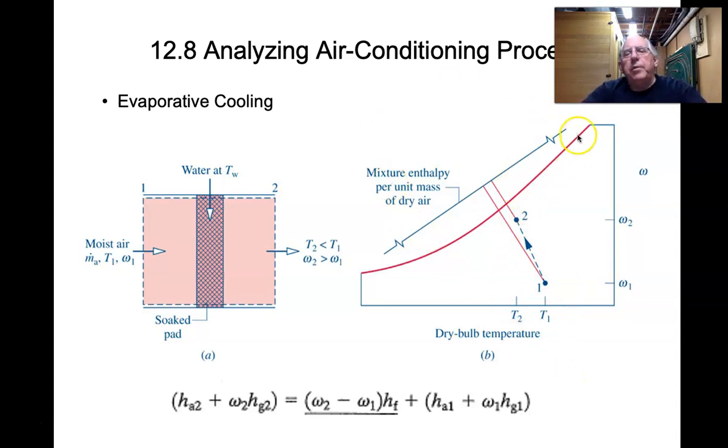And in this particular problem, as they show the mixture enthalpy going from state 1 to state 2, going up and picking up a value, the first law equation, as you can see here, they've separated the components a little bit, such that this term right here, the dry air enthalpy in addition to the moisture enthalpy, at state 1 corresponds to this mixture enthalpy term.